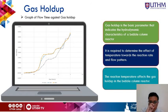Next, moving on to the gas holdup. In summary, gas holdup is the basic parameter that indicates the hydrodynamic characteristic of a bubble column reactor. It is required to determine the effect of temperature towards the reaction rate and the flow pattern. The reaction temperature affects the gas holdup in the bubble column reactor.